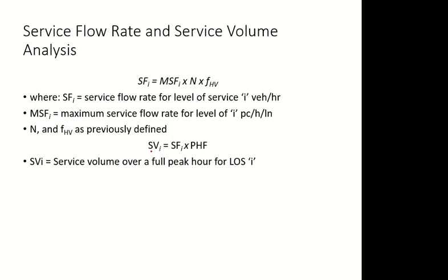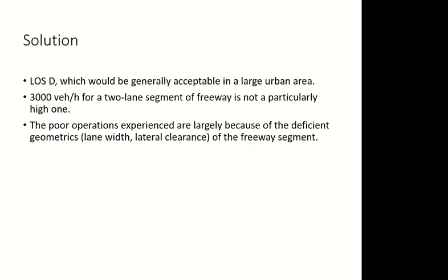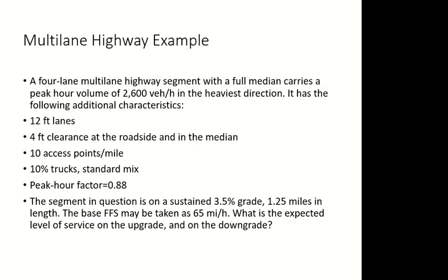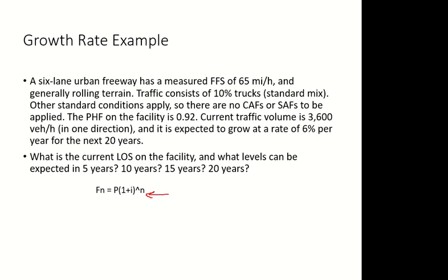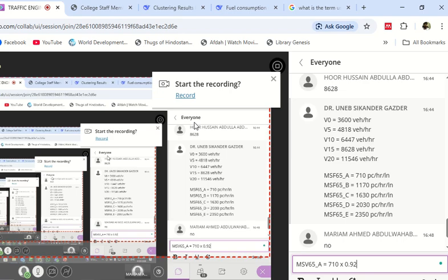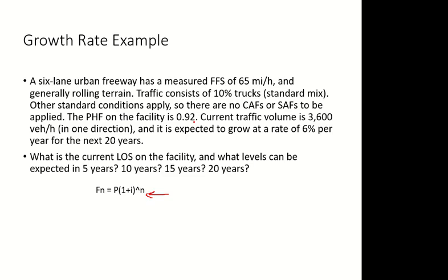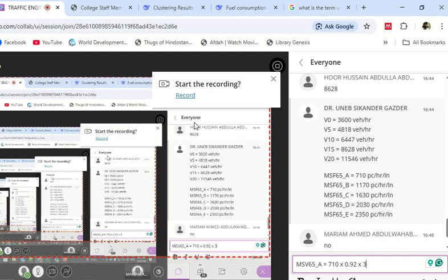So I will multiply by peak hour factor to convert to volume, and then multiply with the number of lanes to convert the rest. Peak hour factor is given as 0.92. Now it has become volume, and to convert the remaining, I need to multiply with the number of lanes. There are 6 lanes, so I'll multiply by 3, one direction.